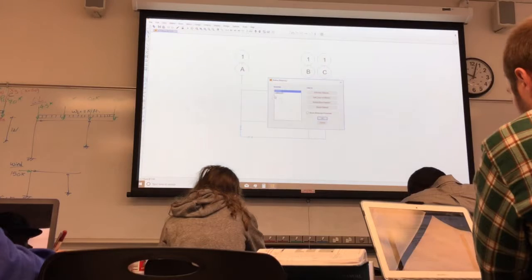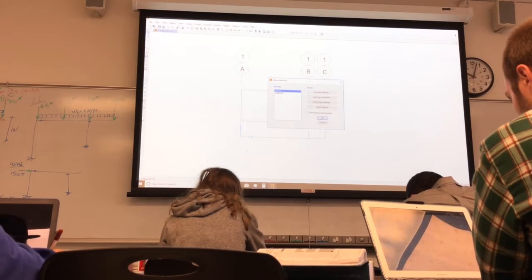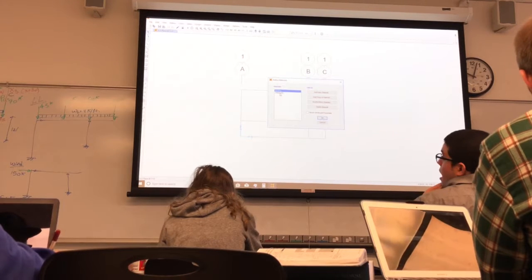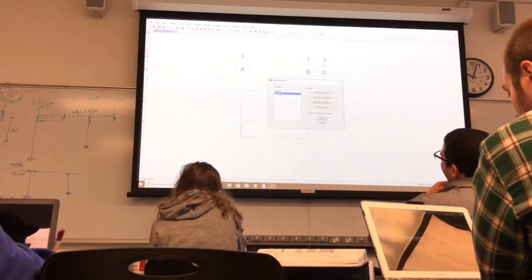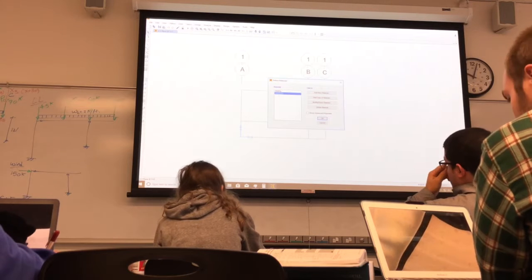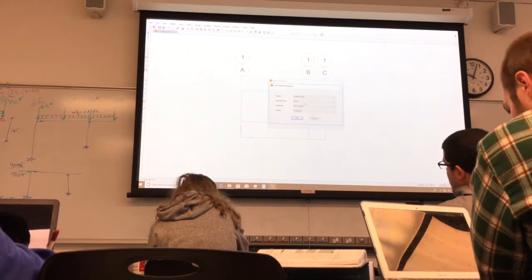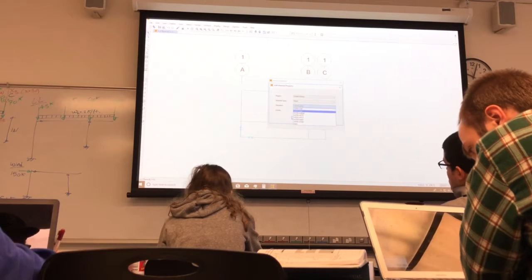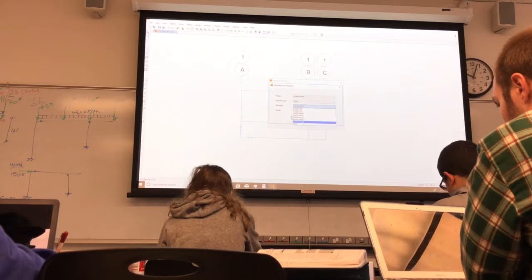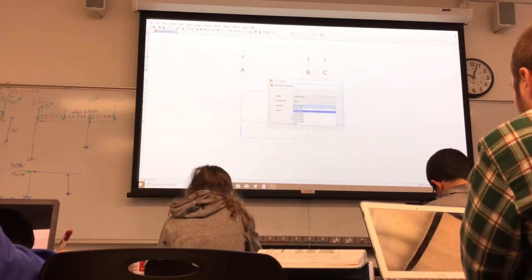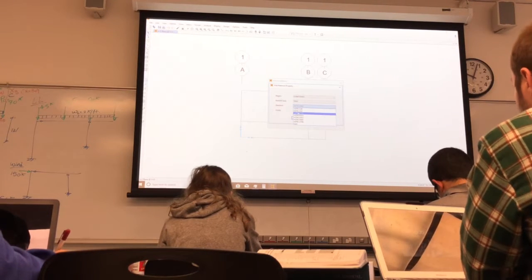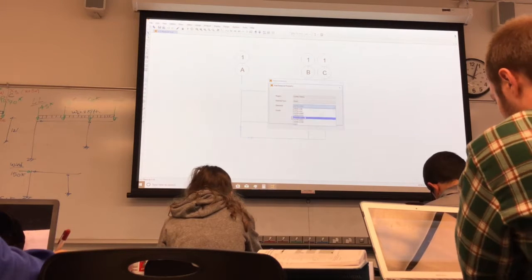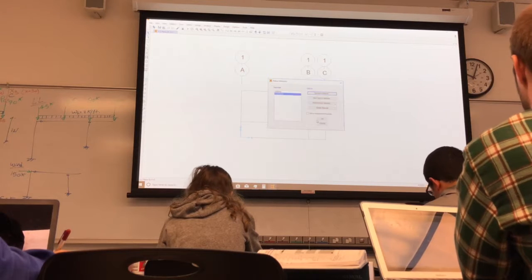SAP is very good software. It already has A992 for us. If we didn't have A992, then we would have to add a new material. We have to go there and add, and it has a library of materials. Like you can see, there's A36, A53, A500, A572, and it doesn't cover all of the ASTM designations, so you can go and have a user specified one. But here we got A992 already, so we don't have to care.